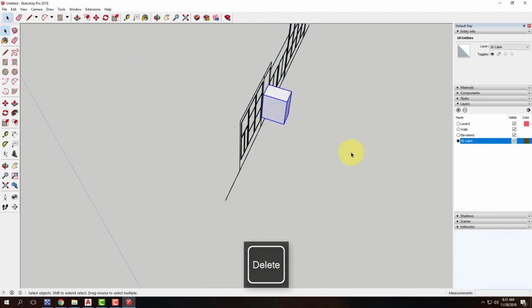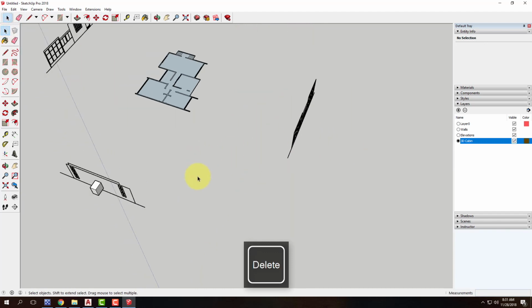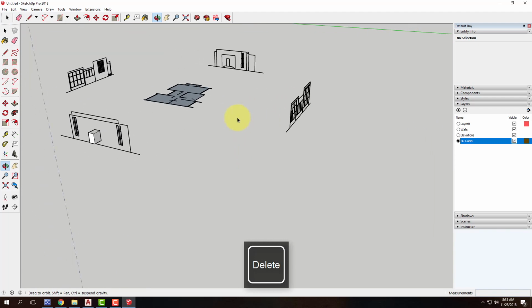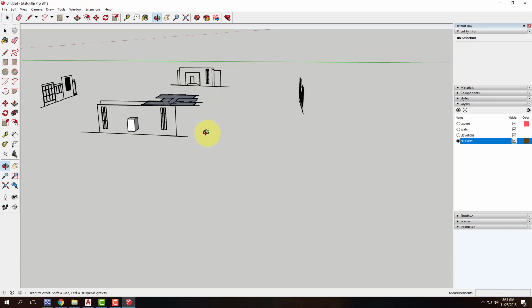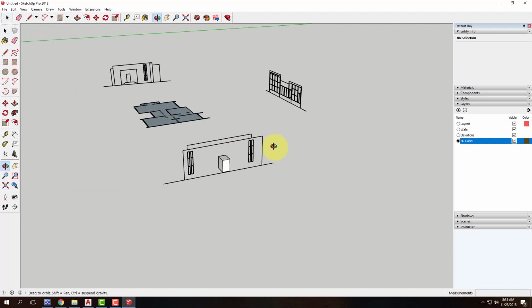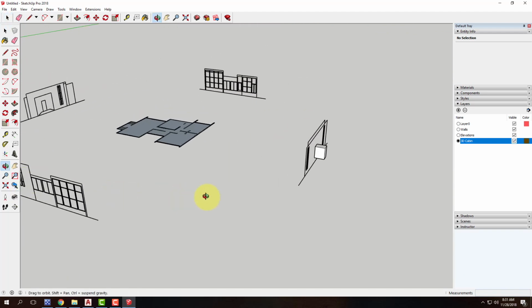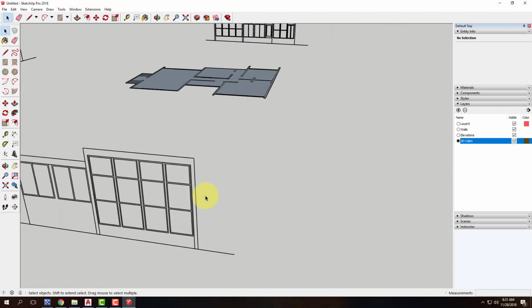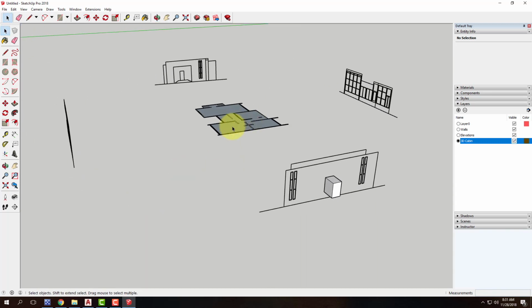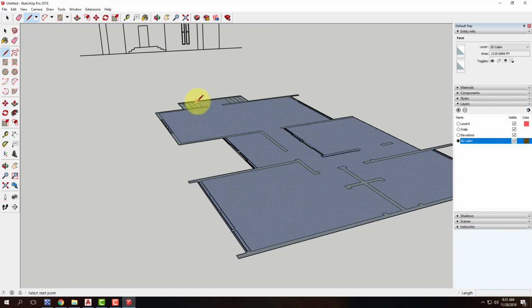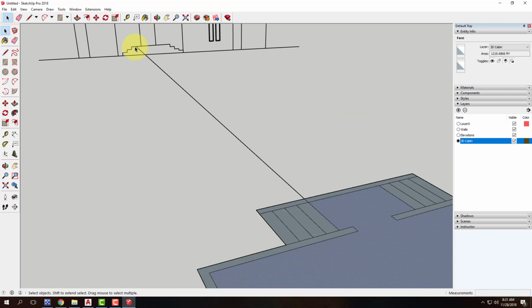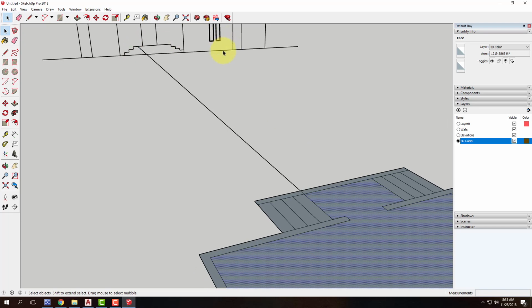So the only thing, though, is after I've made the rotations, I do have to make sure that everything falls at the right height so that my elevations aren't lower than my floor plan. I was really careful on 3 of the elevations with where I rotated from. You guys may or may not be as careful, but I know that this is the finished floor, so I know a few things need to happen. One, this finished floor plane should match up with the height of that set of stairs over here. So it should match up right there, which it does.